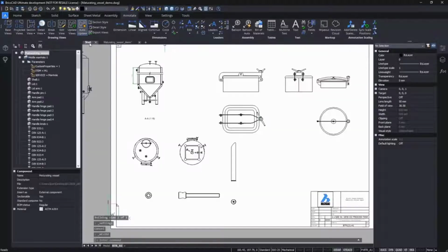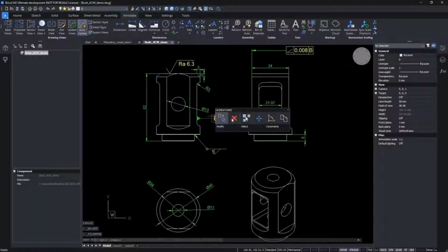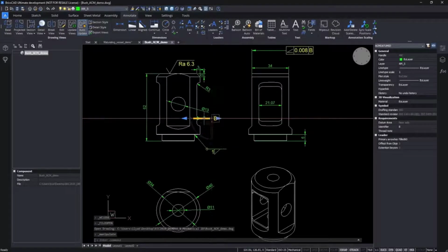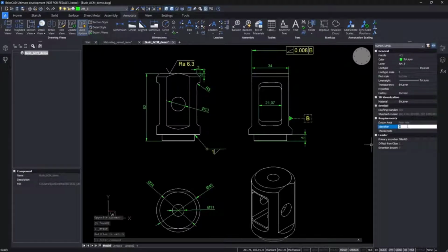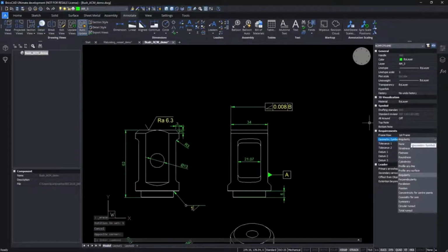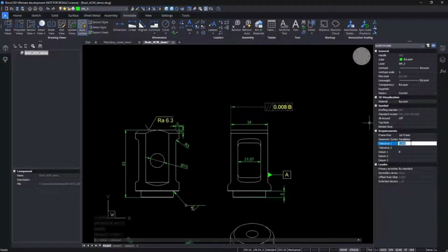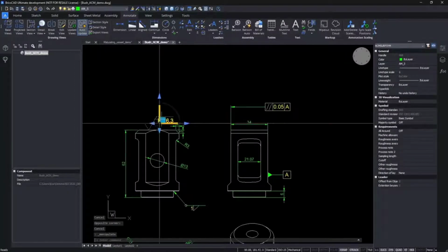After that, you can modify 2D elements. We are supporting copy, move, erase, and other basic operations, but our capabilities are wider. For example, we see how we are scoping the datum ID using the manipulator. In V21, we added the ability to change properties from property panels. We corrected the feature control frame property, and now we're replacing the fusion symbol in the proper place.